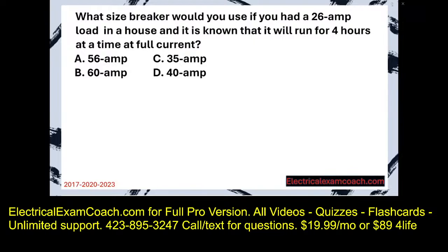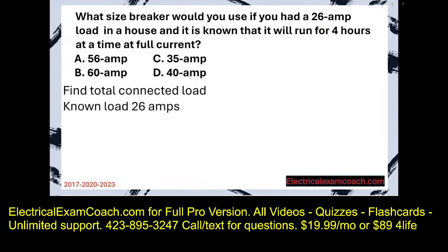What size breaker would you use if you had a 26 amp load in a house and it's known that it will run for 4 hours at a time at full current? Step 1, find the total connected load. Our known load as of right now is 26 amps.